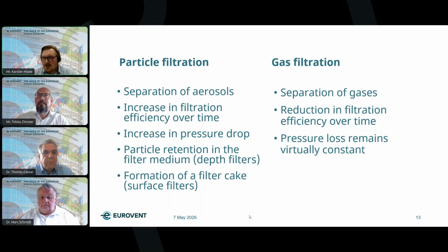Gas filtration is different. So we have two filter types which are hard to compare. Gas filtration, of course, is separation of gases. You have a reduction in filtration efficiency over time. And the pressure loss remains most of the time constant. Of course, not totally, when you have some particles inside or you have some water, when the humidity is high, it gets into the filter. But these are a little bit different. So you can't look at the gas phase filtration like at the particle filters when it's time to change our filters. But this will tell you my colleagues in the next slides.